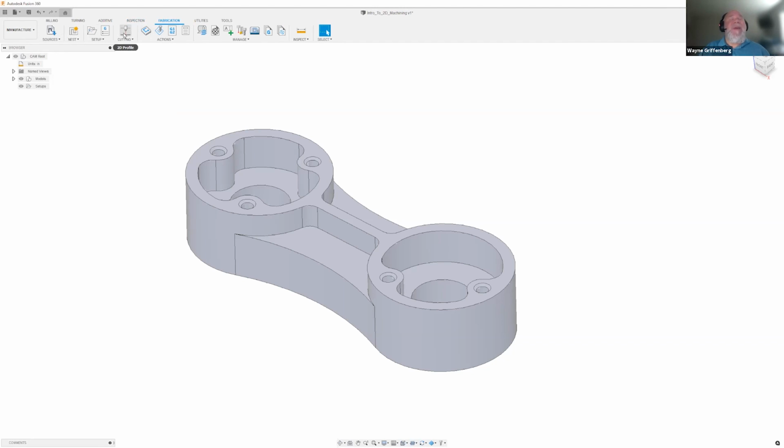And fabrication. So we can run CNC plasma machines or laser or router and different cutters that you can run, even water jets on the fabrication. And with an extension, you can turn on the capability for nesting. So if you make high production parts, if you fill up sheets on your router, or your water jet machine, you can absolutely do nesting. So instead of hand nesting those components, within seconds you can get all the parts of your assembly nested using our nesting extension.